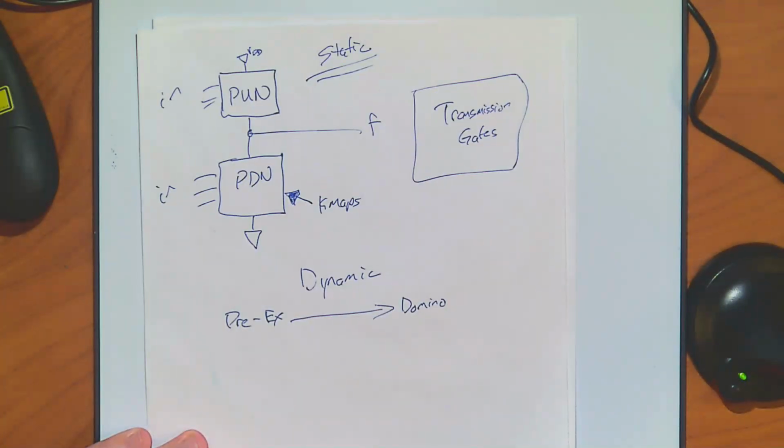Transmission gates are particularly good with the Mux design technique, which, if you remember from your digital logic, is a particularly easy and elegant technique. That's really why transmission gates are very nice to use, because they're good for building on one of the easiest, most elegant design techniques out there. That's just kind of a commentary on them.